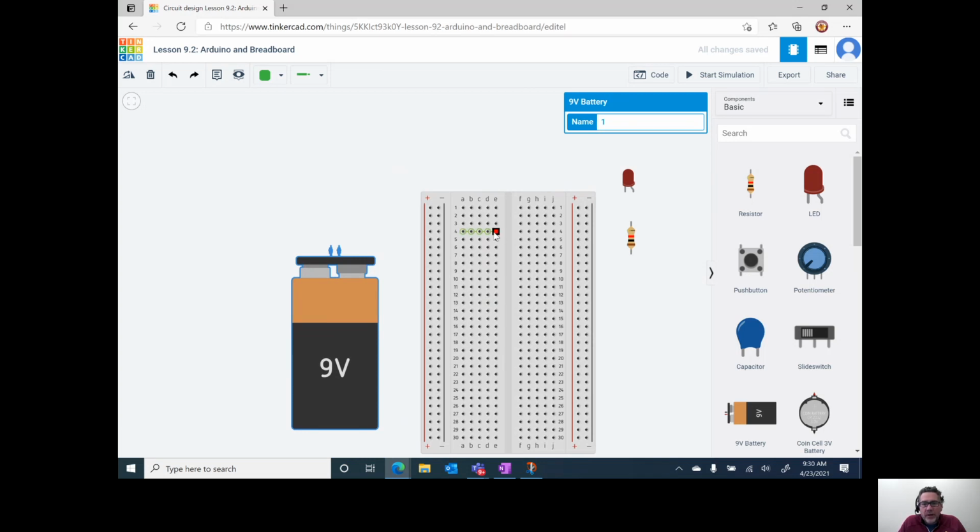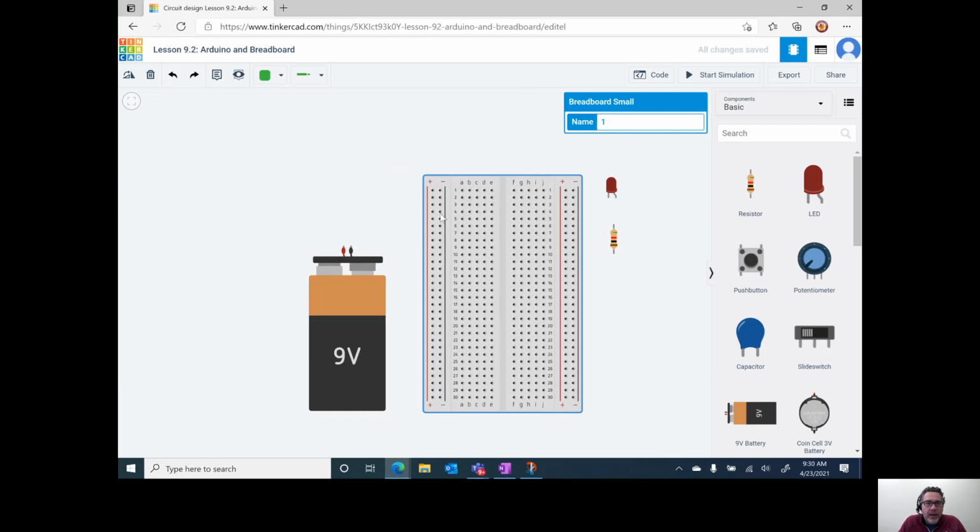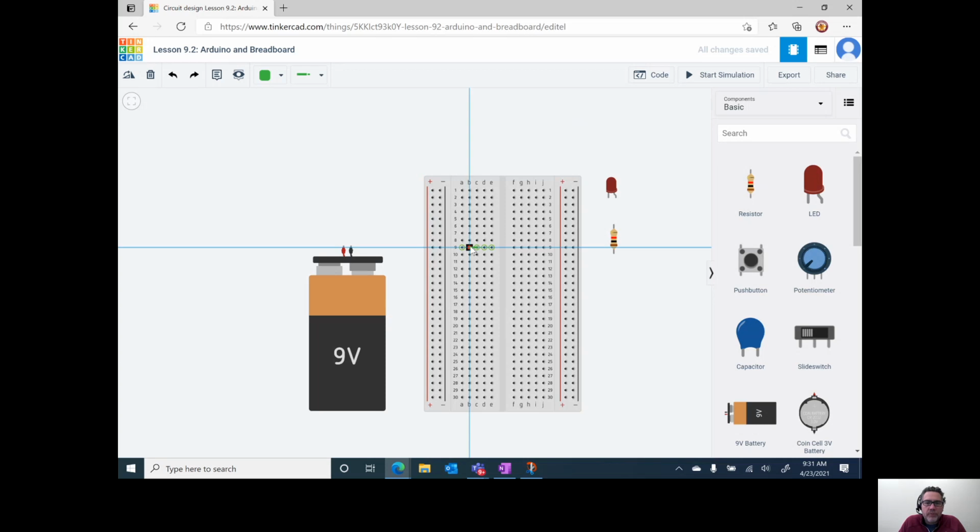So it's basically like a wire running in between these holes. If you put one thing on one side and another thing on the other, they're going to be connected with that wire. The other thing that a breadboard has is these on the side, they've got long vertical connections here. So this would be the positive and this is the negative. The reason we do this is for easy connections when you're trying to power up multiple things on your breadboard, we can run them through that. Okay, so I'm going to show you how we're actually going to set this thing up.